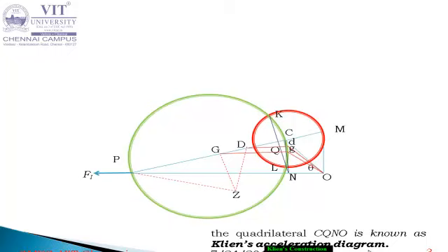So you have to draw one line which intersects the line of stroke, which is the acceleration of P. That is the point of the acceleration of both the masses. Both accelerations intersect at one point, so that point is taken as E.